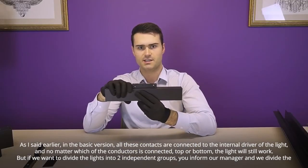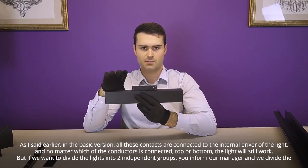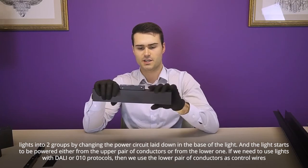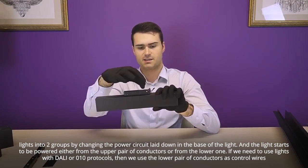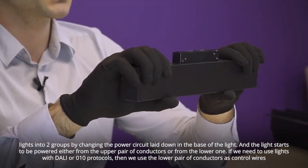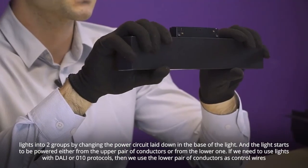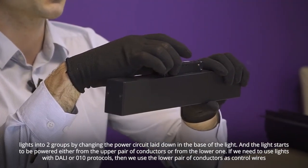But if we want to divide the lights into 2 independent groups, you inform our manager and we divide the lights into 2 groups by changing the power circuit laid down in the base of the light. And the light starts to be powered either from the upper pair of conductors or from the lower one. If we need to use lights with DALI or 0-10V protocols, then we use the lower pair of conductors as control wires.